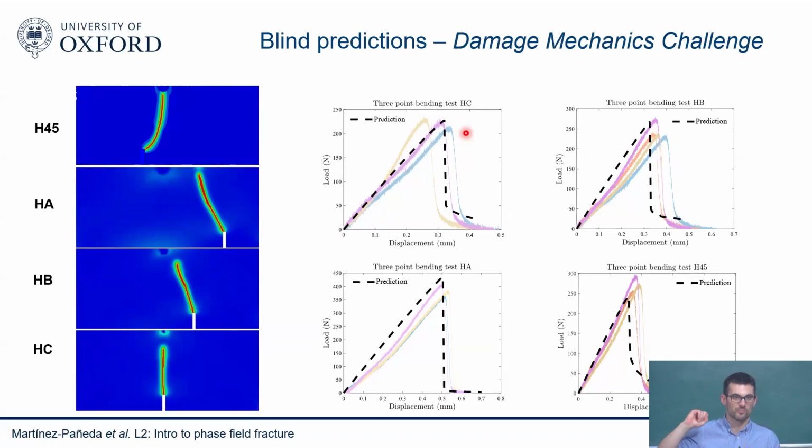They gave us one test. If they didn't give a single test and we say we are 3D printing this material, let's say Portland cement, then we will have data for Portland cement maybe in the absence of 3D printing, from conventional methods. So we'd have to extrapolate from our toughness and strength to how porosity influences toughness and strength. Since they gave us one and they printed all with the same method, we could calibrate strength and toughness with one, and then we could predict the other ones.